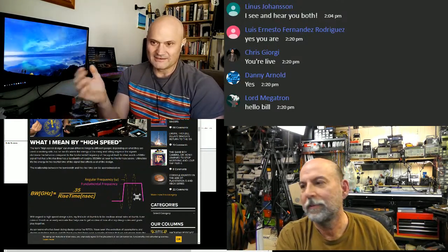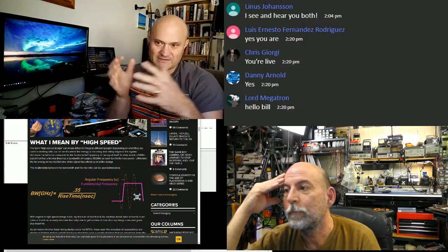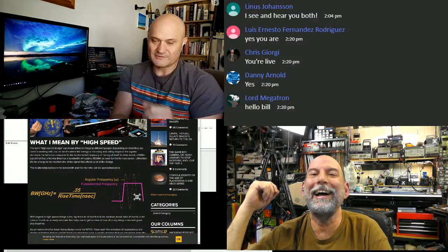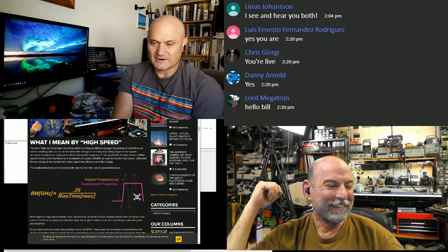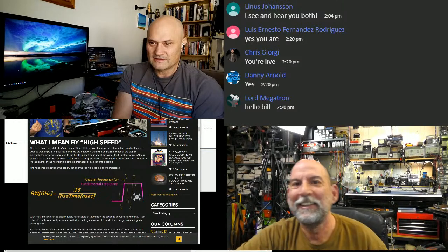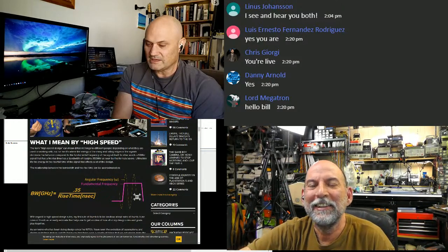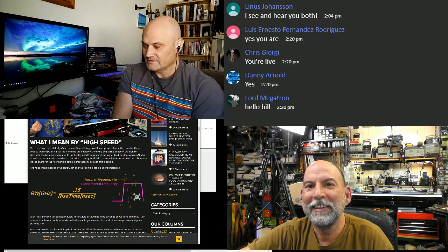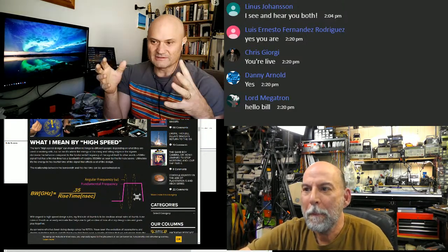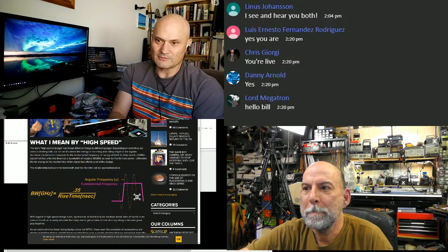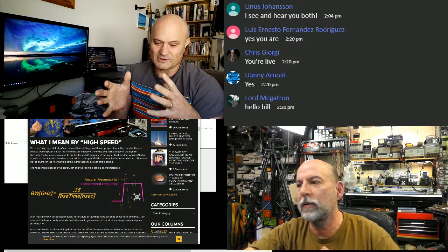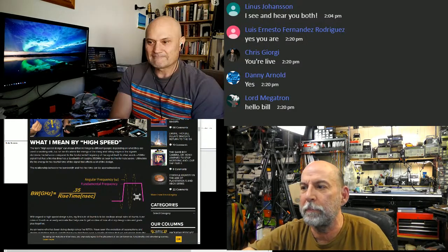They said, and we did a basic transmission lines class. We had huge coils of low loss coax, right? And we'd actually measure them with oscilloscopes. We'd do TDR stuff, but we did it with actual oscilloscopes and pulse generators. So we knew how a TDR works. TDR is time domain reflectometer, which tells us how long it takes for a signal to come down and back.